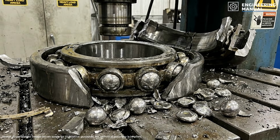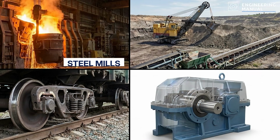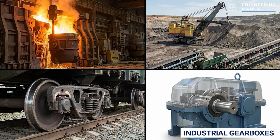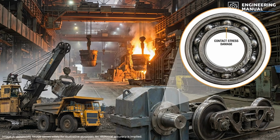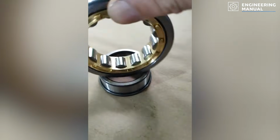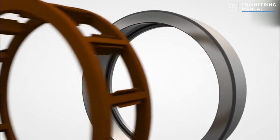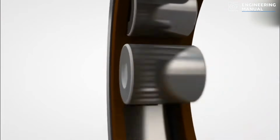This is exactly the problem engineers encountered in heavy industry: steel mills, mining equipment, railway axles, industrial gearboxes. The contact stresses inside ball bearings eventually become too high. The obvious solution isn't stronger steel, it's changing the geometry. Replace each ball with a cylinder. Instead of touching the raceway at a single point, a cylindrical roller contacts it along an entire line.